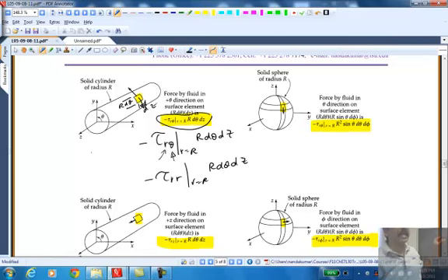And there is also a tau r z. So I can calculate all three components of the stress acting on that surface. Of course, we need to know how to calculate the shear stress. That we are going to do later on, in terms of the gradients of the velocity field. If I know how the velocity changes from the surface, I can calculate its gradient, then I know the shear stress. Then when I integrate that shear stress over the entire surface, I get the total force caused by the wind on that cylindrical surface.